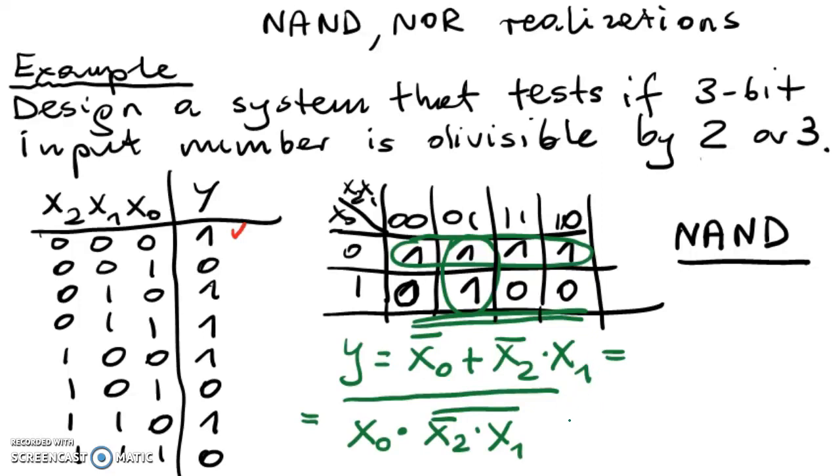So what you've got is a NAND. It's also NAND, and NOT is needed here. So if you have only NANDs, one of the 2 possibilities to get NOT using NANDs is in this way. You simply connect the 2 inputs together to have an inverter. But very often, because NOT is cheaper than NAND, you've got at your disposal also NOTs. So let's do this in this way.